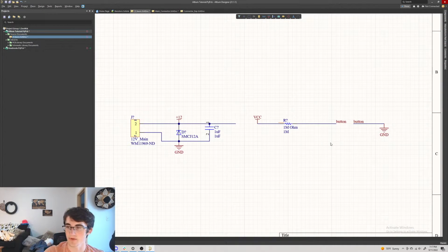Also, one handy tip with the power ports: whatever you set your power ports to after your switching regulator or whatever power circuit you have, like this is the standard 12 volts, this is the 5 volts, this is what we're going to use for any capacitors that are going to be decoupling, anything going to our microcontroller, this or that. Always copy it from whatever you started with for the power ports instead of going up to the top and placing it, because they might get mixed up.